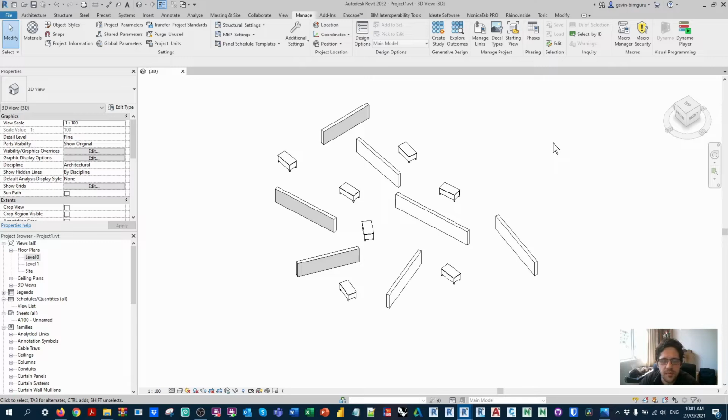So in this case, we're going to be looking at a method that can assess the rotation of these elements, because as you can see, a lot of these elements have been rotated against Project North, which is also Dynamo North. In this case, it's technically the internal north or the internal origin's north facing direction. So if your project has a true north rotation, it's not going to be accounted for in how Dynamo interprets the rotation of its bounding box when it looks at it against the axes of Y. So in this case, we're looking at axes aligned bounding boxes.